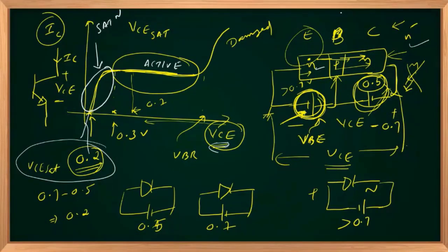Positive P, holes will move towards right. N region, electrons will move towards left, right? Towards left. No current is constituted by the emitted electrons from the emitter because the second junction is forward biased. It completely blocks the minority carriers. And that current, holes flowing towards right, so holes leave the collector. Whereas initially in active mode, you should recall that collector current flows into the collector. But if this junction is forward biased, collector current leaves the collector, right?